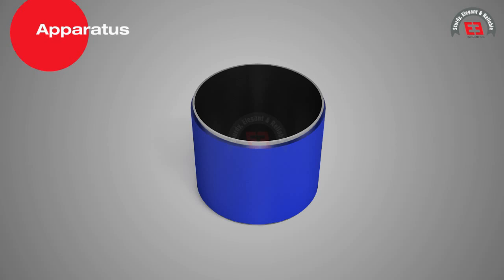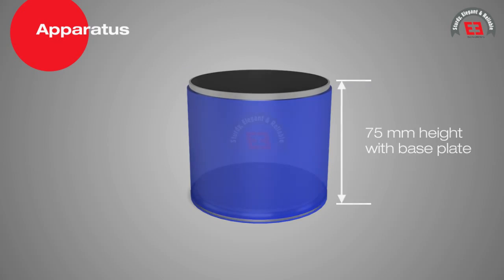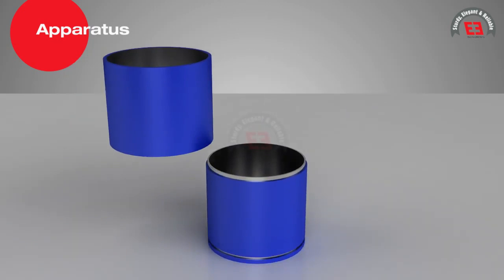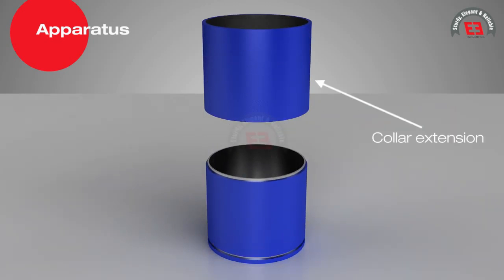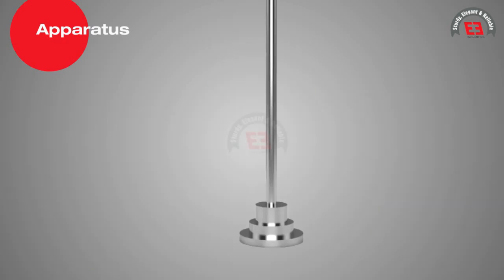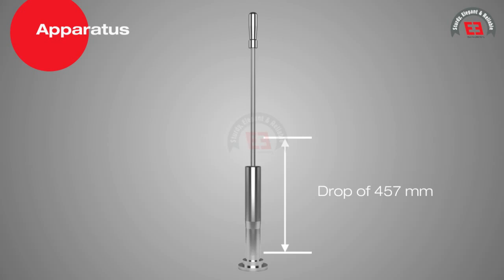Apparatus consists of a cylindrical mold of 101.6 mm diameter and 75 mm height with base plate. Both the ends of the molds are interchangeable on the base plate. A collar extension is provided for preparation of sample. A compaction rammer with a flat circular plate of a diameter of 98.4 mm with a hammer of weight 4.5 kg, which can be lifted and released to obtain drop of 457 mm.